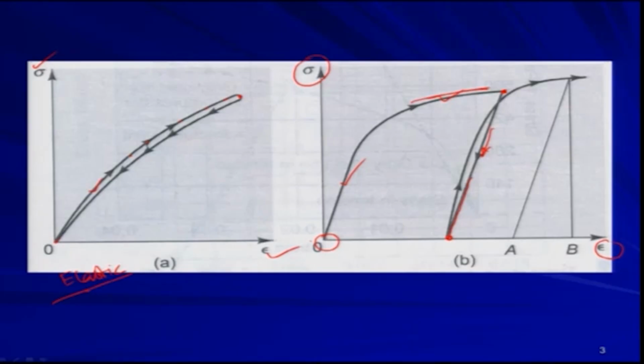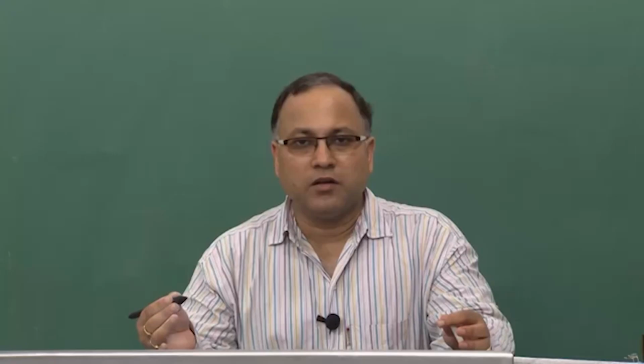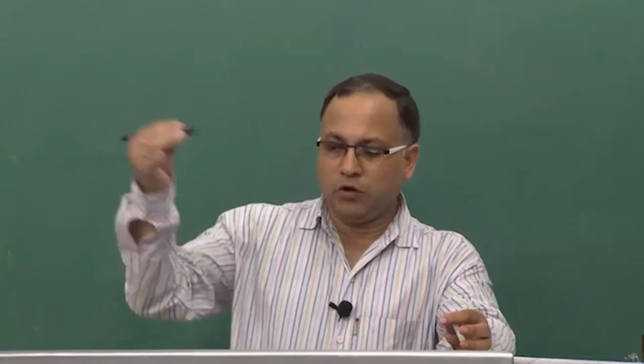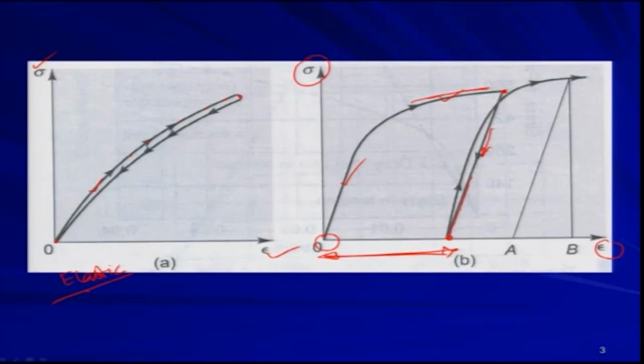So, therefore, some plastic deformation is happening. This much of plastic deformation is happening. This much of permanent deformation you are observing due to the unloading. Though the load is not there, load is 0, the stress is 0, but still you are not able to come back to this original position.